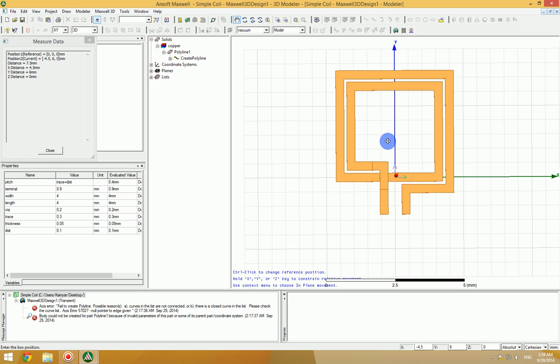Then when you calculate the Maxwell equations inside that, you have quite a good amount of accuracy, as if it's inside an infinitely large area without any boundaries. So it depends how large you want to go, how accurate you want to be. You have to make it larger and larger. In this case, I'm going to make it not very large because I'm going to do some simulations and want good, fast results.